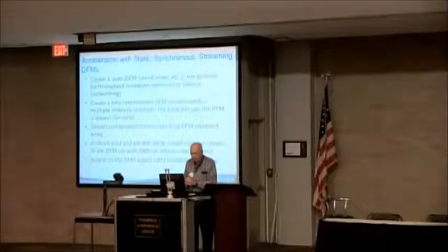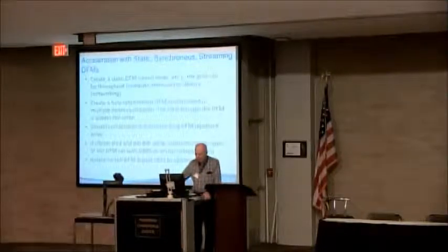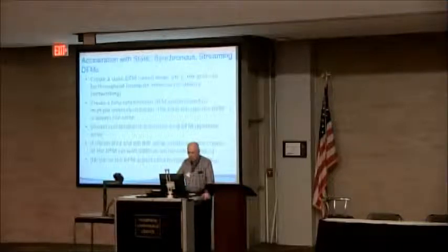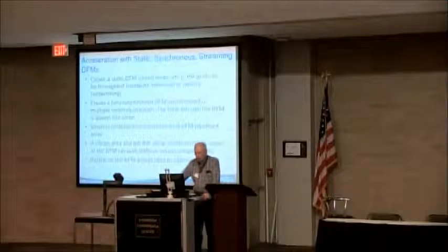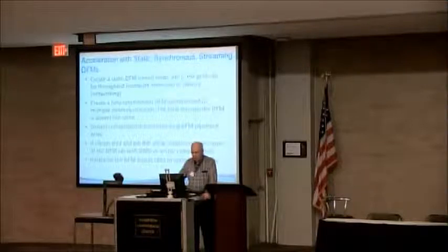The time through the data flow machine is always the same because it's static. And we're going to stream computations along this long data flow pipelined array. We're trying to use all of the pin bandwidth of the FPGA and all of the silicon area, insofar as we possibly can, to maximize the speed up.